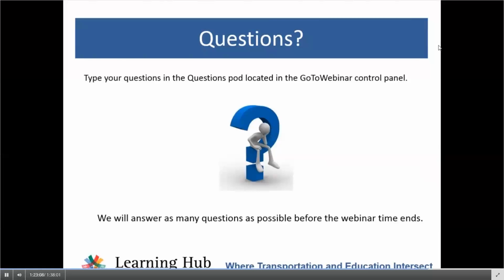And so I think perhaps the best illustration of that has been the very positive experience we've had with the majority of diverging diamond interchanges. When you talk about service interchanges in urban and suburban environments, they're notorious for being not pleasant places to walk or bike. And yet with the DDI, not only can an agency fix what is probably a congestion and safety problem, they can also carve out the space to provide a very pleasant walking area and also on-street bicycle lanes or shared use paths, whatever the case may be.